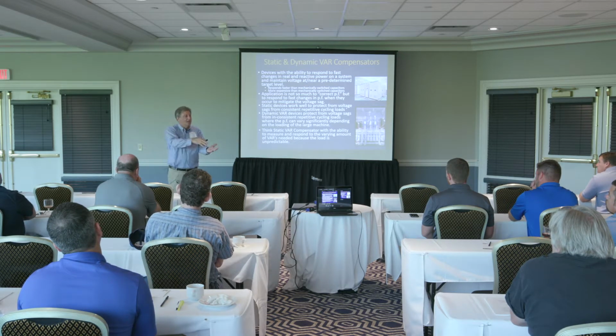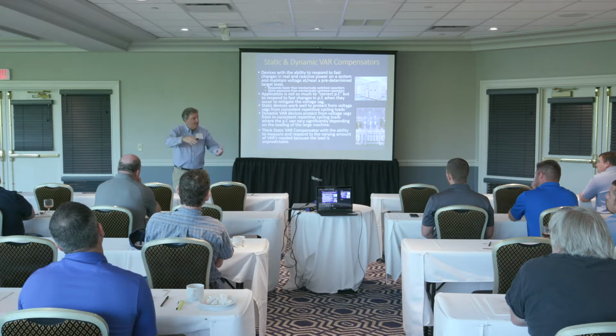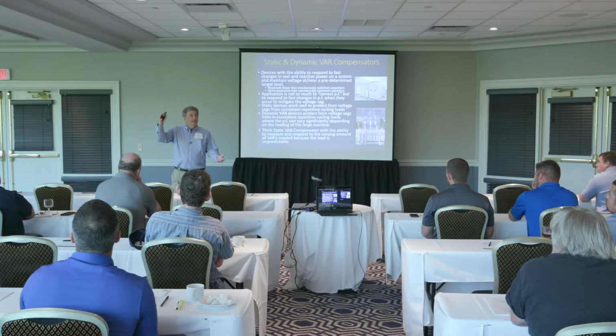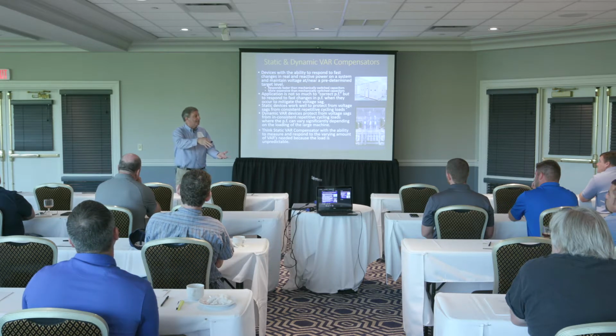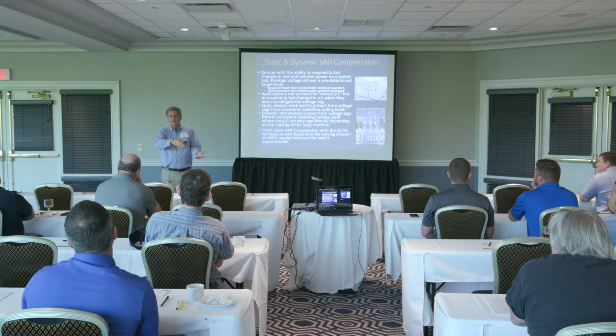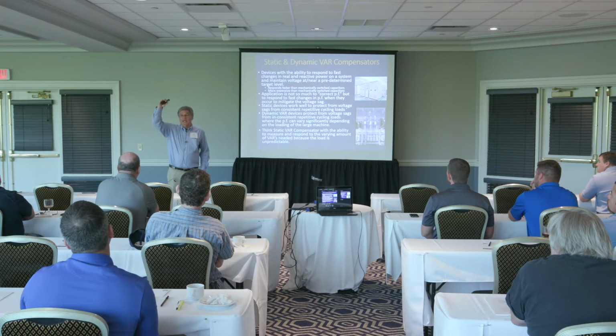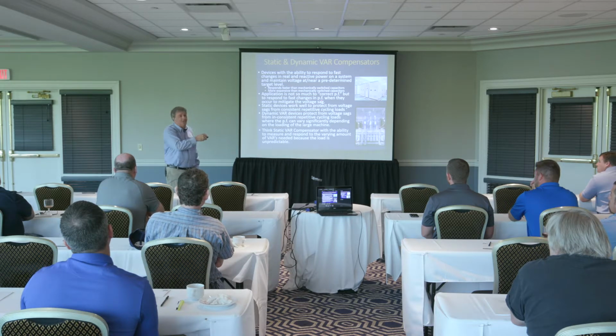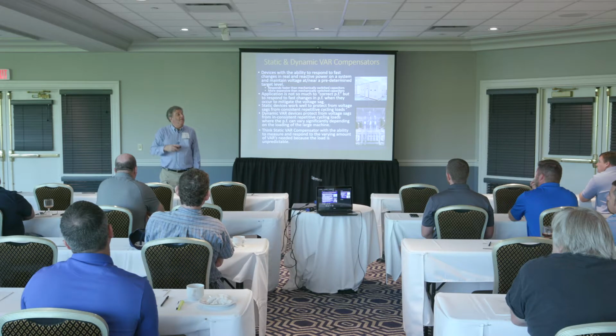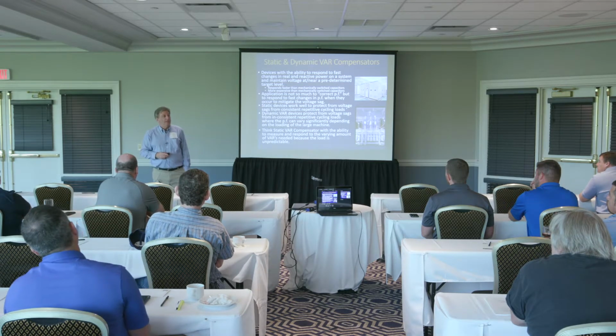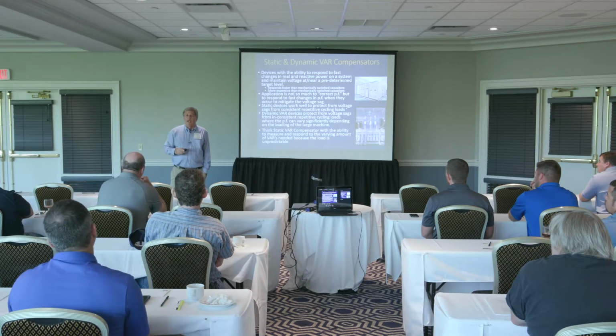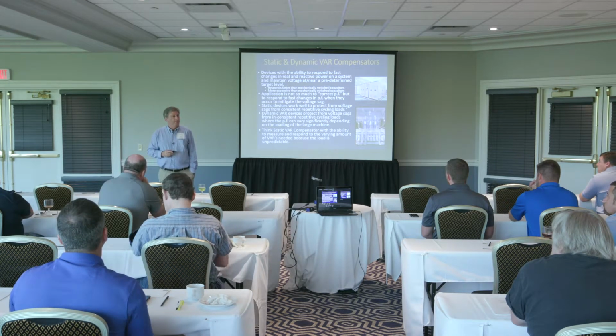Crushing the car, I need more amps to crush that car. And now all of a sudden, it's only there for 30 seconds, 40 seconds, the car's crushed, and then it goes away. And during that time where those big amps and the inrush of that car crusher hit, that voltage could drop quite a bit. And all of a sudden you're complaining about voltage sags from your co-op. They're potentially causing electronic controls to trip or lock up.